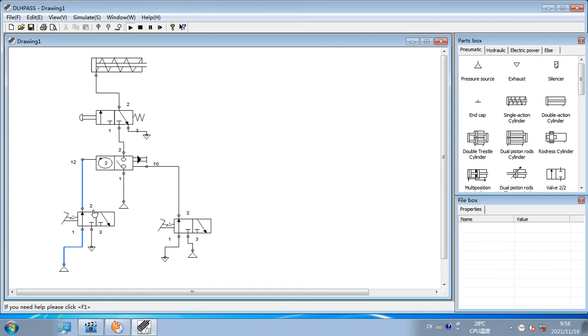But this is being pressed, so it won't. This is a resetting button, and this is a set button. So you press this and you can see it's counting. Then release, it counts. Then release, then it counts. You can see when it reaches 0, on the count of 0, contact is being made, and pressure air flows from the pressure source to the pneumatic counter and into the pneumatic hydraulic, and pressure goes into the pneumatic cylinder.